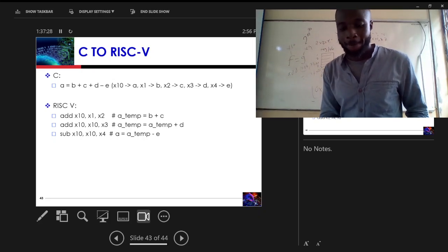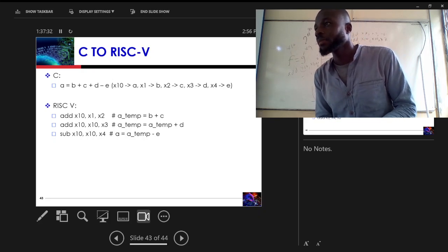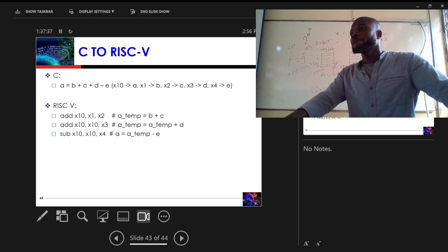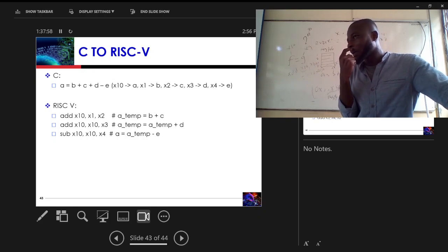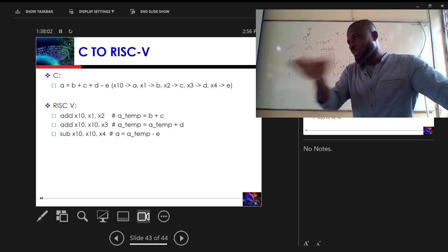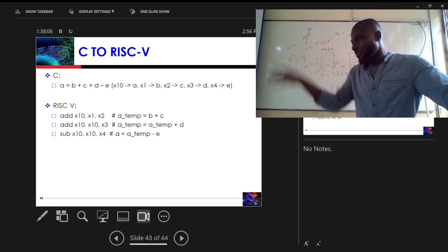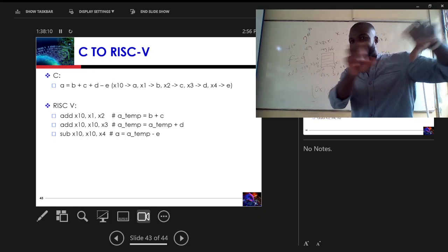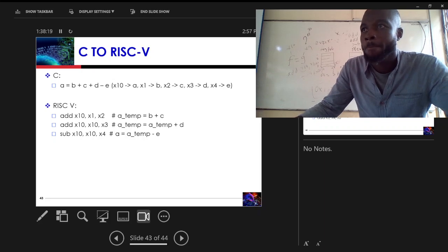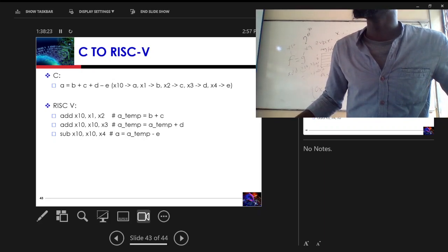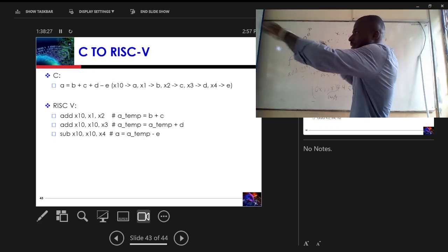Any question? Yep. When we are doing it by 4, registers. I wanted to ask, since X0 is hard coded, does the whole row... No. Those ones are the addresses. They are not the values in the register. They are address 0, and then we refer to this memory location address. I'm not talking about the register file. The register file is where X0 is hard coded, not memory. The memory itself is completely different from the register file. The register file is just 32 bits and it's fixed. Yeah, that one is fixed.